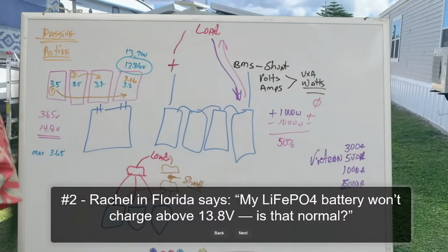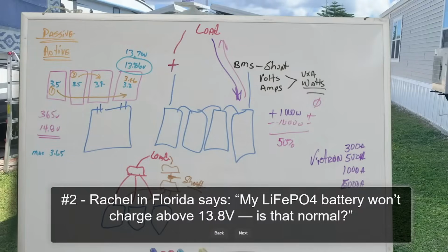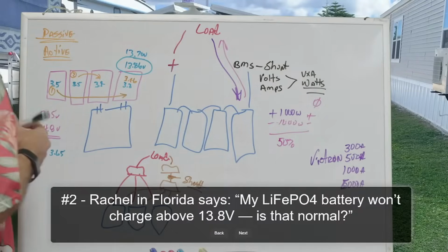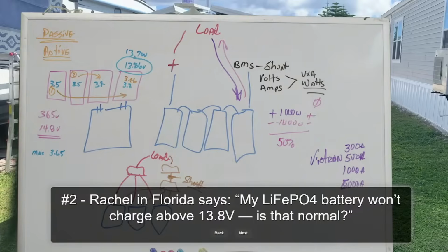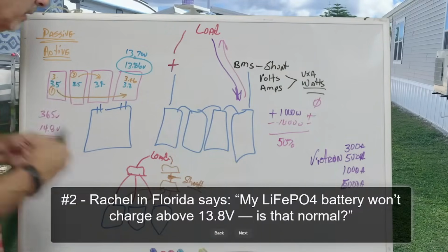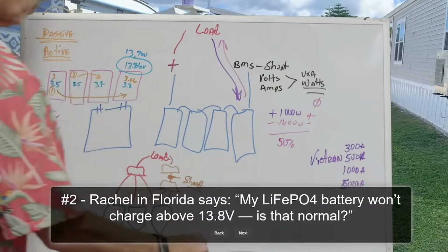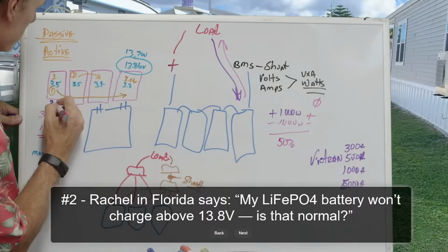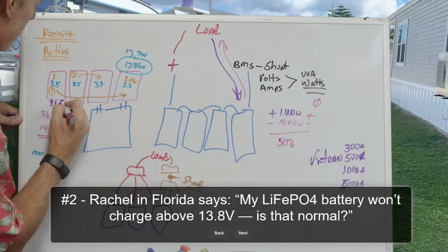And what the passive balancer does is it basically burns energy from the high cell through resistive loads and heat. So it would basically take this 3.6 volts that this one originally had, 3.66 volts I think it was.